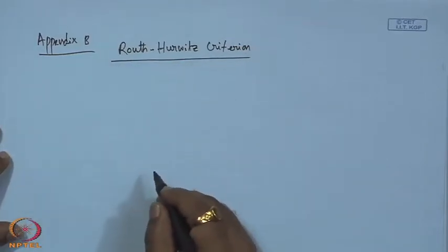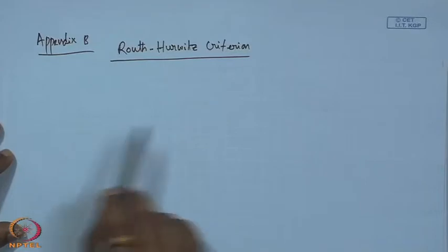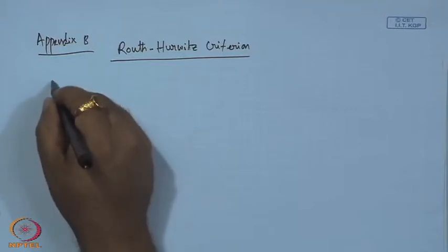Many times, in order to get stability, we end up with a polynomial and we have to find the roots of this polynomial, or sometimes the range. Finding all the roots is quite complicated. So, at least if we can get the region where the roots lie, then we can conclude the corresponding stability. The Routh-Hurwitz criterion is very popular, and it indicates how to compute the region of stability. Okay. So, let us have a look at it.